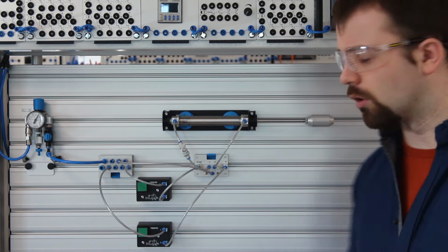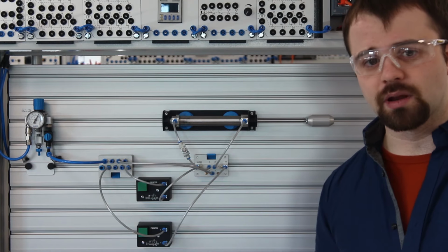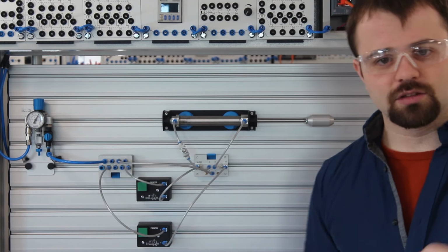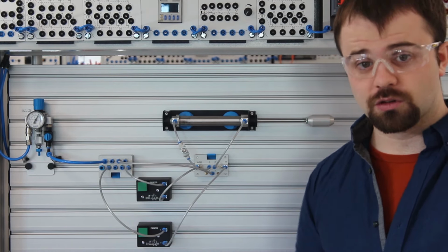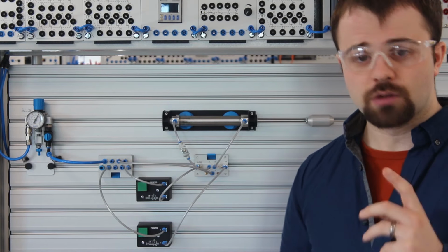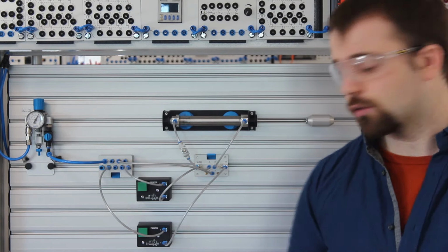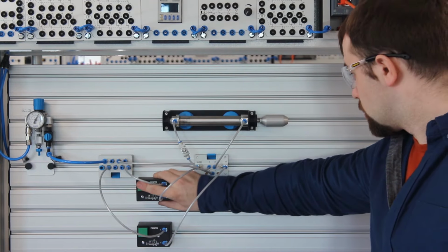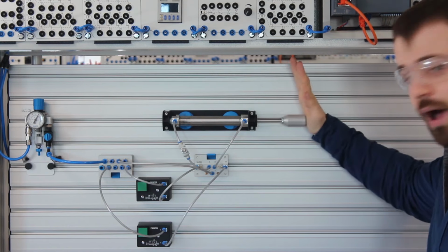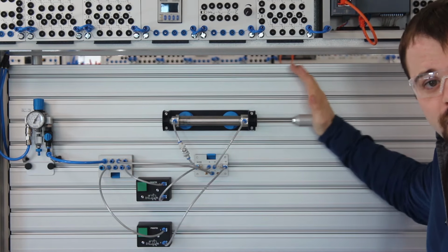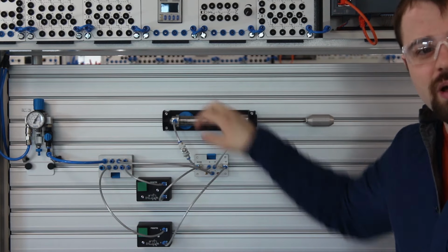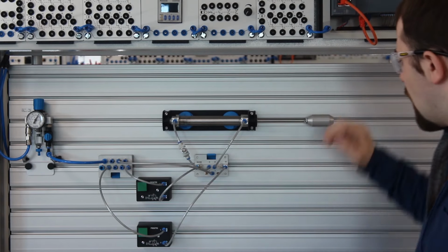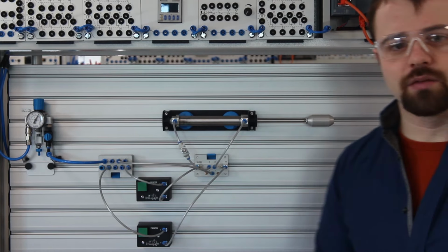This might look like the perfect solution, but it almost poses a problem in itself. Because we're restricting the speed at which air is going into the cylinder, it means the cylinder is not extending with the full force that it's capable of. Let me show you an example. Don't try doing this yourself, because you might catch your fingers. If I bring the cylinder back, and then start it going forward again, you'll notice that I am able to push it, and it's kind of springy. I can push it forward and back. That's because the pressure inside is not at 6 bar, it's being restricted by this, and there's a lot of room for wiggle. And it means that this can be quite a problem if you're not pushing forward with the full force that's required.